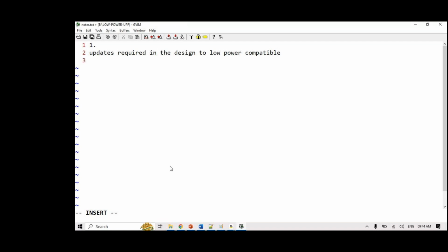And then we'll also talk about how to set up the UPF. How do we partition the design into multiple voltage domains, power domains? Those things we'll talk about, and how to implement UPF in that case. How to implement the UPF, and then how to use those UPFs that we have developed for individual modules to set up the UPF based test bench, and we'll run those simulations, and then we'll analyze the output, whether it is coming as per the expected behavior. So that is one thing I'll be doing.